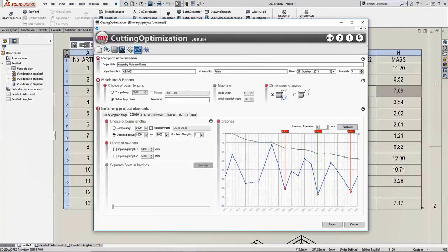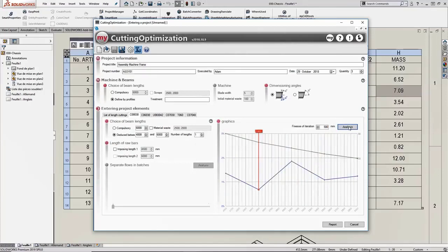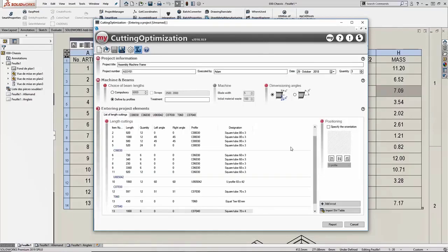If I increase that to 0.5 meter increments for lengths to buy in, then it will show us the most efficient lengths to buy, in this case, which is 4.5 meters. So we can then set a compulsory buy-in length for 4.5 meters if that's what we choose to use in our project. It means we're getting the most efficient use out of the material.